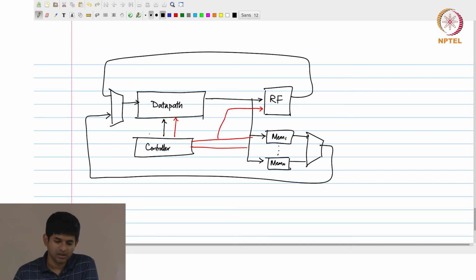In general, when we are talking about hardware architectures, these are important concepts to keep in mind, because for all the hardware designs that we will be looking at, we will primarily be using a tool called high level synthesis for the rest of our design process. All of it will involve this kind of structure. There will be some elements of the code that you write which will get inferred as the data path, the computational elements, and the rest of it is basically a question of figuring out the control logic around it, and providing the right signals to the controller.